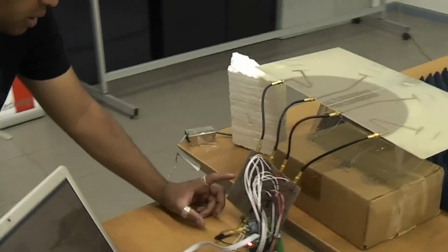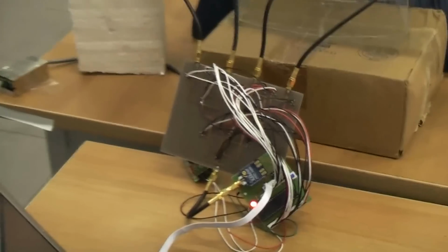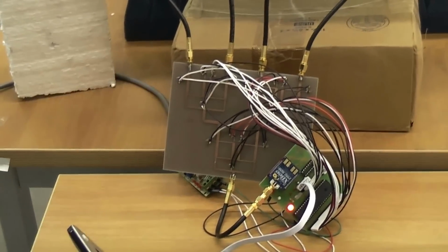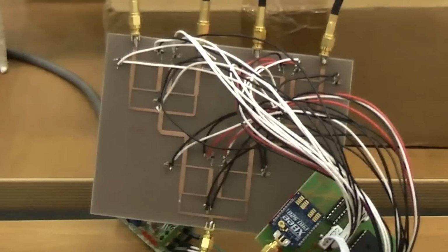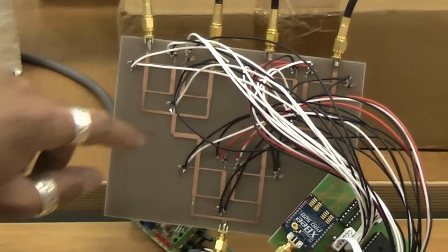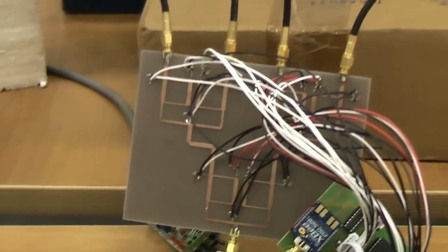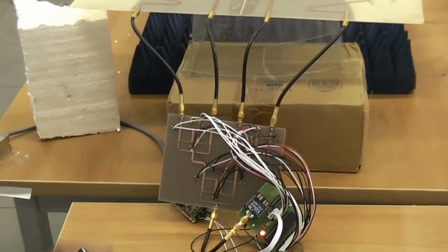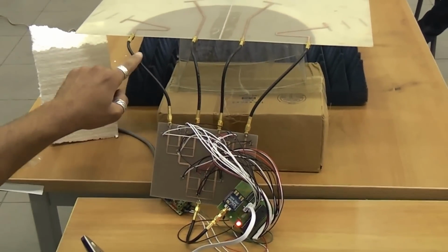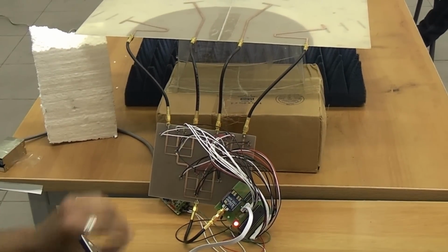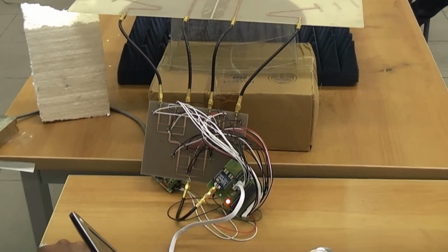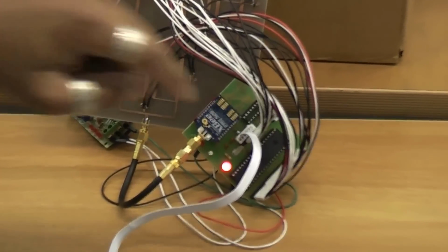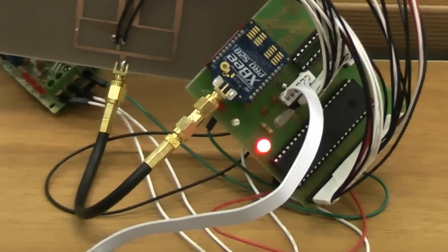Our feeding network here is composed of 3 different switchable couplers. Our couplers are composed of RF switches. These switches are used to direct the power in different directions. Actually, we are using them to feed the network's 2 terminals at the same time or direct all the power to only 1 terminal. All the switches and all the schematics for the different configurations of our switches are controlled via our PIC microcontroller.